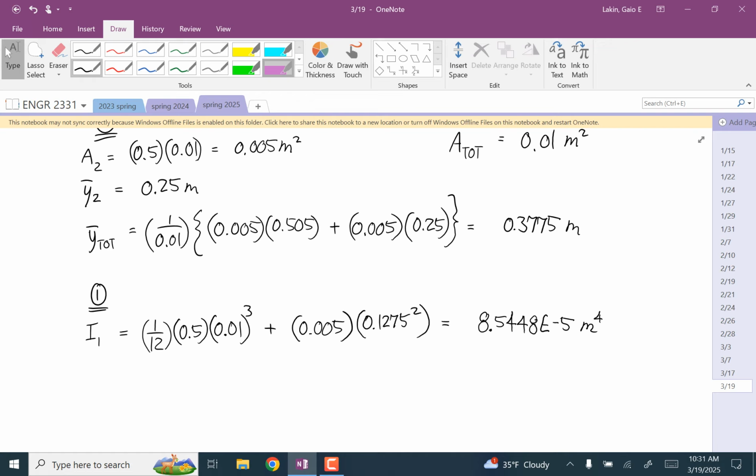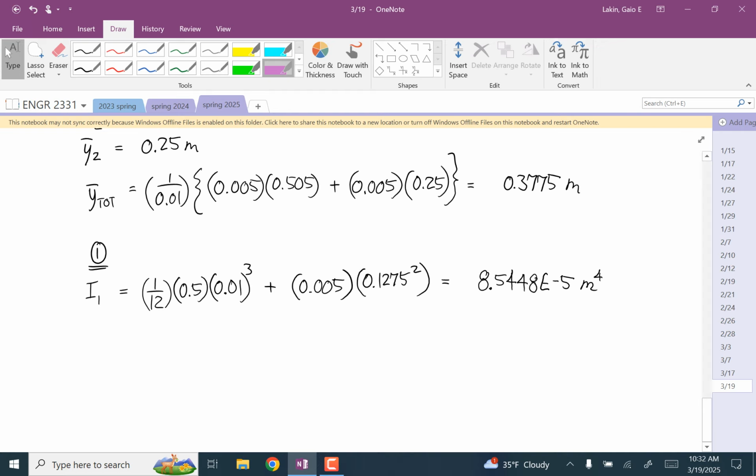It just has to do with the bending formula. And I wrote that in the notes last time. We haven't used it yet, but the stress due to bending is just the bending moment times the height above the neutral axis divided by this I. And so if you can make this I big, you make the stress small. Okay, so now the second shape,